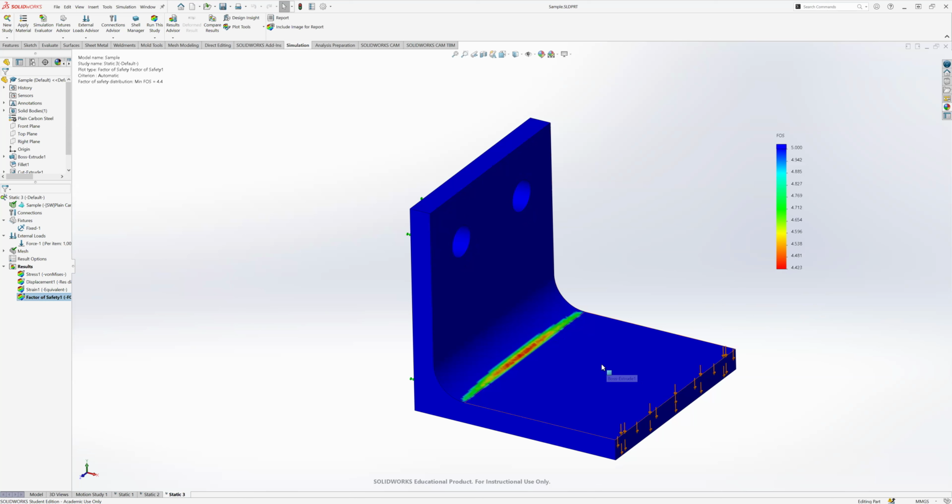But a lot of times those cutouts will cost money to machine. It takes longer to machine it. So your stock is going to be the same. Let's say you're using angle stock, or just a bar stock. In that case, you may not really care that the factor of safety is high, unless obviously weight is a factor. But let's say it's just a bracket that's going to mount on a wall. You really don't care if it weighs a little bit more.